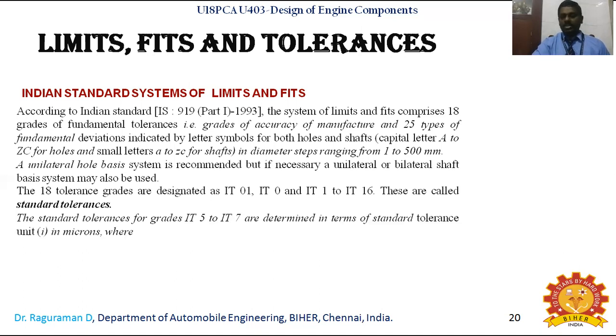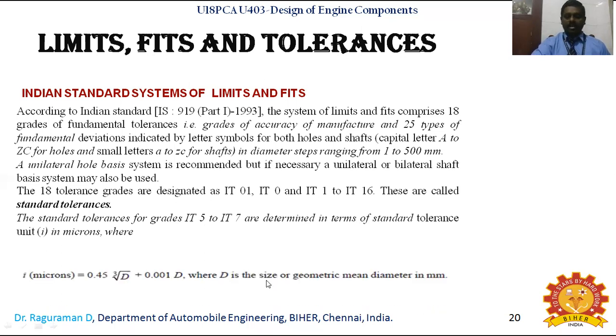The standard tolerances for grades IT5 to IT16 are determined in terms of a standard tolerance unit i in microns, where this unit i can be identified using the empirical relation i = 0.45 cube root of D plus 0.001 D, where D is the geometric mean diameter in mm. As D is in mm, multiplying with 0.001 converts it into microns.